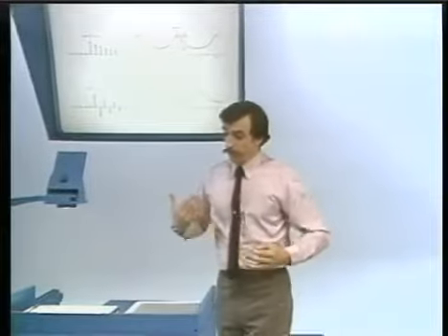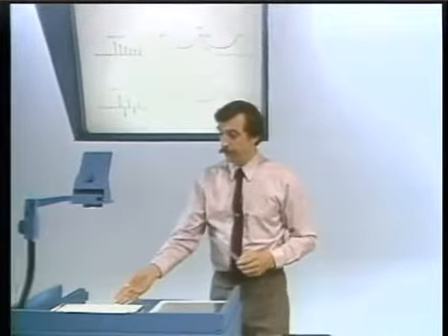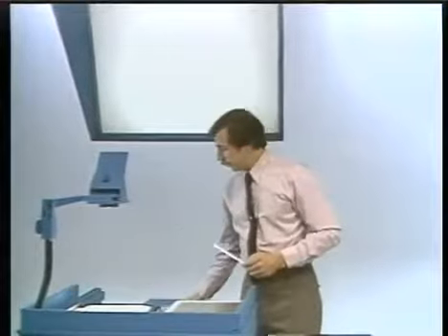Okay, so we see that in fact a first order difference equation is a filter, and in fact it's a very important class of filters, and it's used very often to do approximate low pass and high pass filtering.